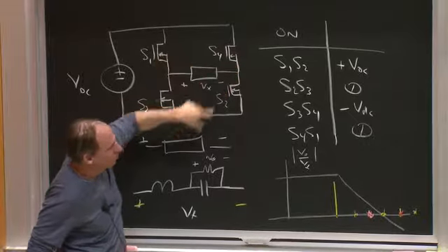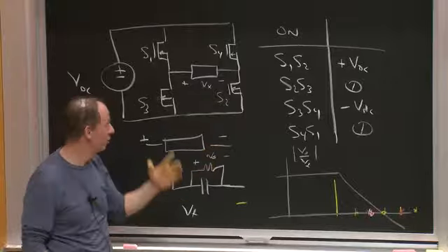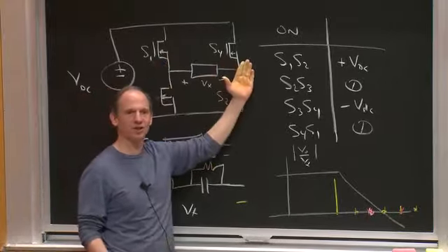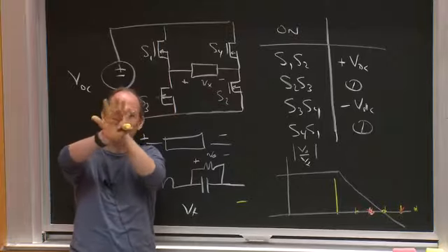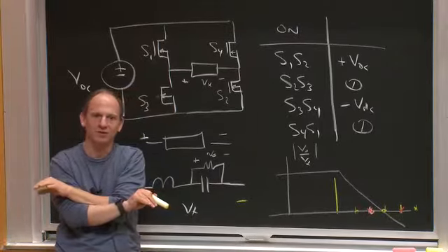So in fact, the one pulse per cycle waveform that I showed you, you could really view it as a cancellation because I have 2 half bridges that are each generating square waves, and I get a harmonic cancellation between those square waves, killing the triplen harmonics.